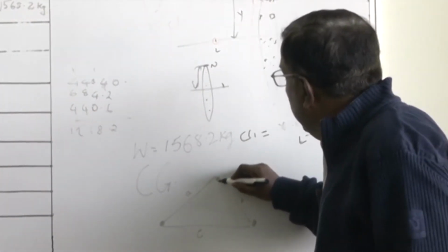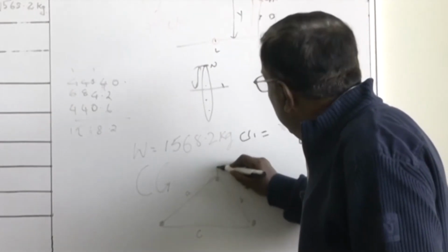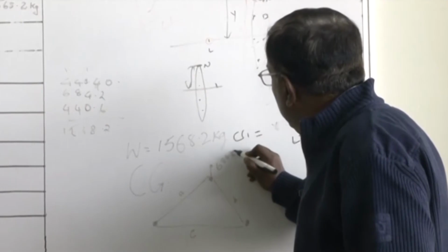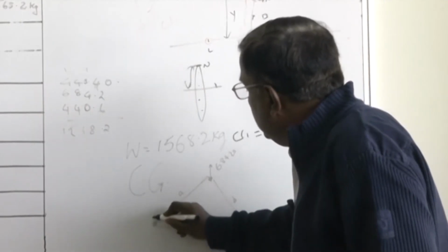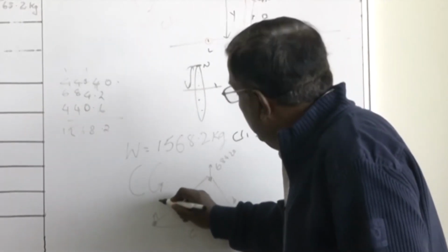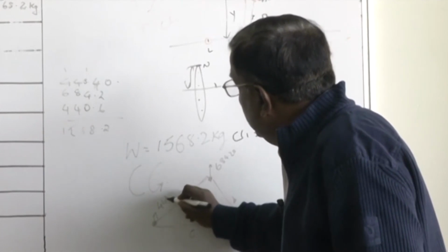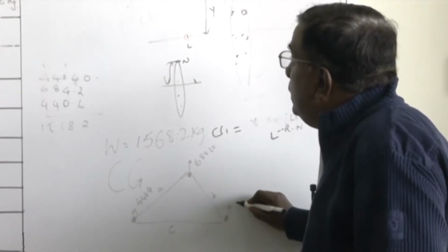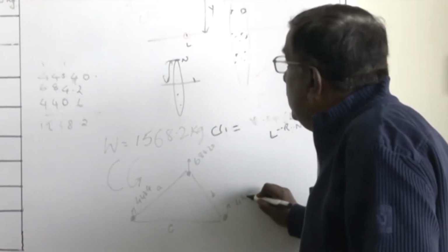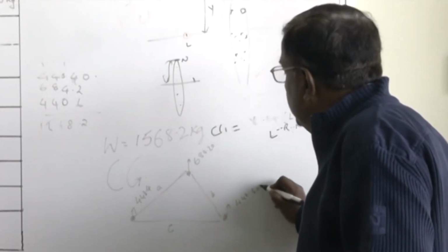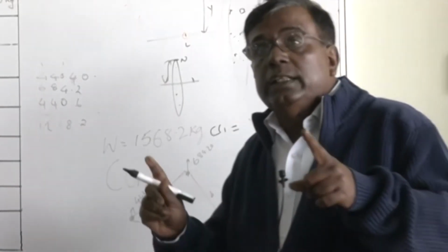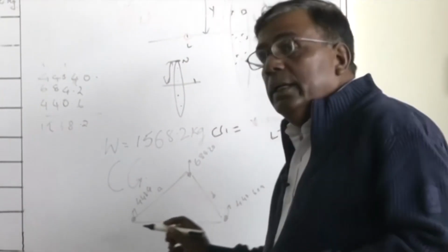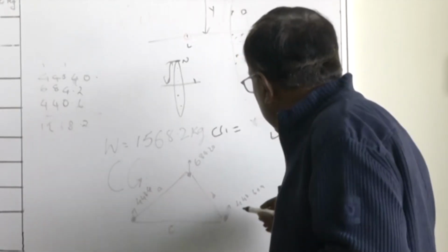So what is the reaction here we are finding? It is around 684.20 kg. And here how much? Left is 443.4 kg, and here how much? 440.60 kg. One thing you can clearly see that this left and right landing gear, they are almost measuring equal weight.